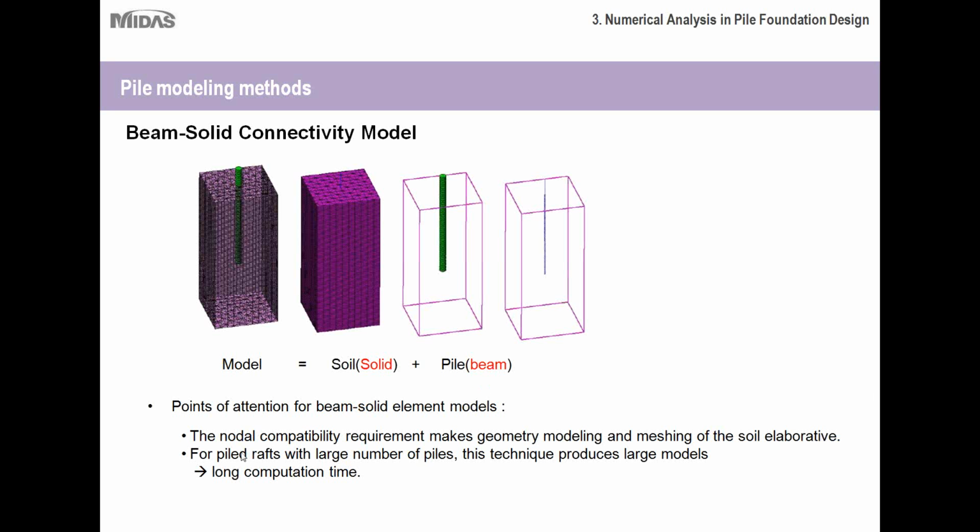As I just said, for pile rafts with a large number of piles, this technique produces large models with a very long computation time, mainly because nodal connectivity needs to be established. And when you're on a project that's being designed or worked on over a period of time, naturally there are going to be changes. So it's not really realistic to use this type of model for a large scale pile raft foundation. Once again, this type of model would work better for a small scale project, maybe a single pile or a pile group, similar to the other method I just showed you.